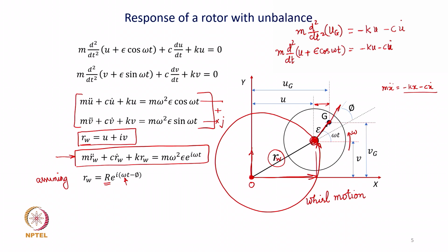This is valid most of the time, because the rotor is going to whirl with the same frequency as the rotational speed, since unbalance is the excitation force here.